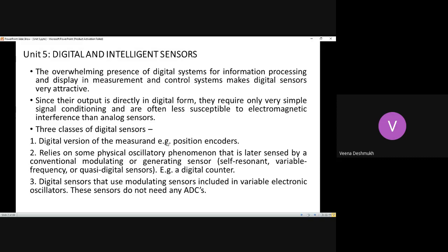It could be an amplifier, it could be a resistor, it could be a capacitor, or even the lead wires also can generate spurious noise signals due to drifts or any other additional parameters due to signal conditioning, or the grounding effects or the reference voltage effects. So all these are possible because there is a surrounding conditioning network involved in the sensing also. Whereas in case of digital sensors, whatever is sensed by the sensor is immediately converted into its digital equivalent.